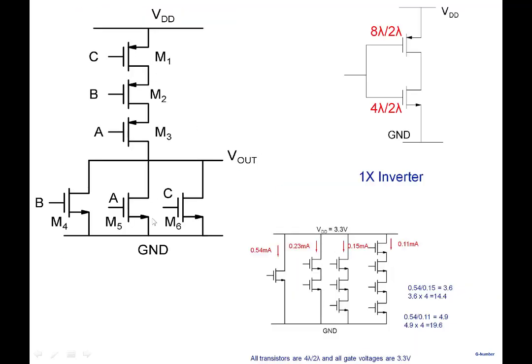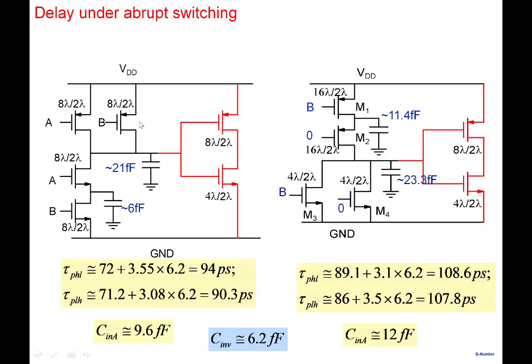If we build a 3-input NOR gate, things get even worse in the sense of transistor sizes. Sir, in the last slide, what do we define the input resistance? Well, like there are input capacitance. Input capacitance. There are options that we can connect to, like B for B only there. No, so for example, you can connect the two B's together and look at the net capacitance here, or you can connect the two A's together. So note that two A's will be connected together, two B's will be connected together. So you have two input capacitances, A and B, and to first order they're roughly the same, and same here.